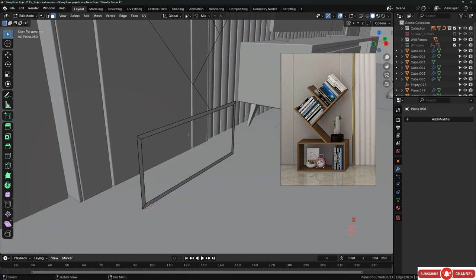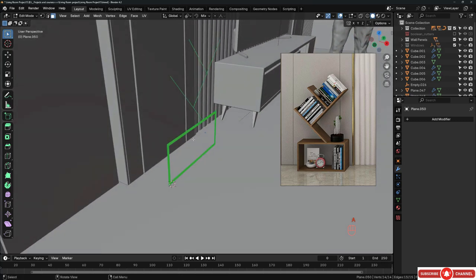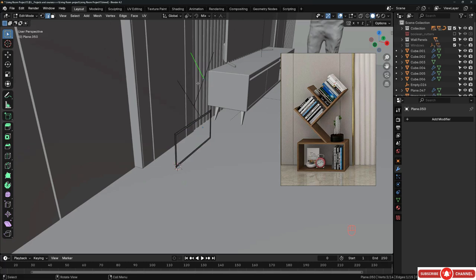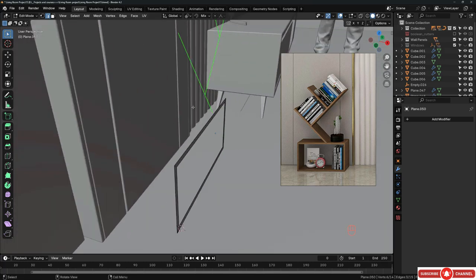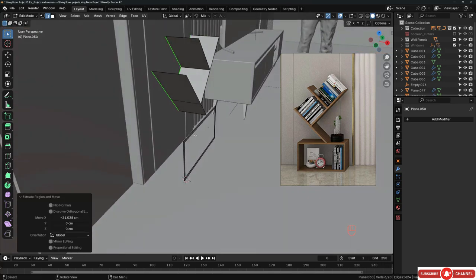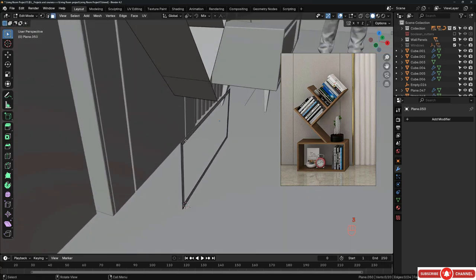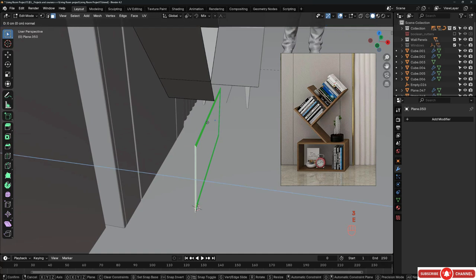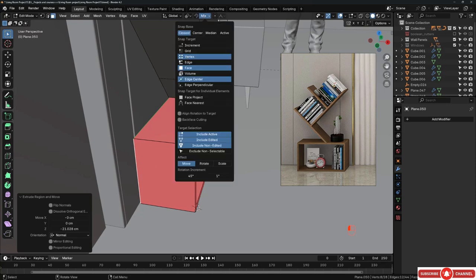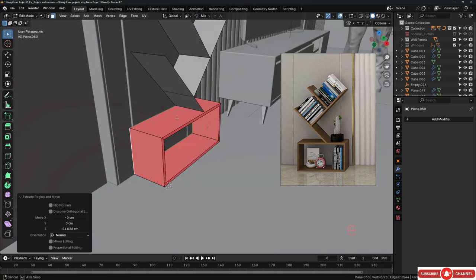And this face in the middle, we don't need it. Hit X, F, and get rid of it. All right, now I will select these edges. We can start with these edges like that, and I will extrude them back like this. And now these faces as well, go to the face, alt click and extrude these, hit E and extrude this, and you can snap it with this corner like that. And to snap it, you should activate vertex snap, don't forget that.